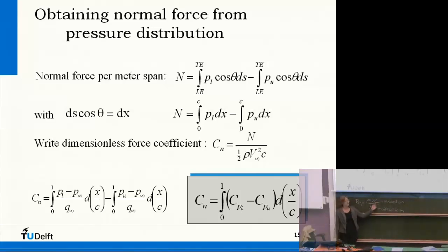So, for example, if the L changes in our wind tunnel, what we do is we change the V to try to keep the same Reynolds number. And there are even cryogenic wind tunnels in, I think, Stuttgart, somewhere in Germany, where they change the rho and mu. So they work with nitrogen, a different gas, and different temperatures to really try to keep this Reynolds number the same. It's quite an issue in wind tunnel tests. Yeah, so that's why it is important.